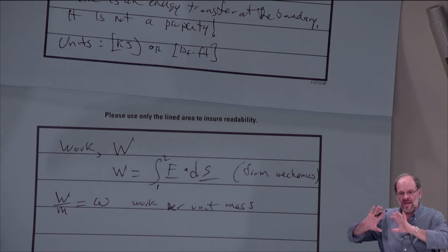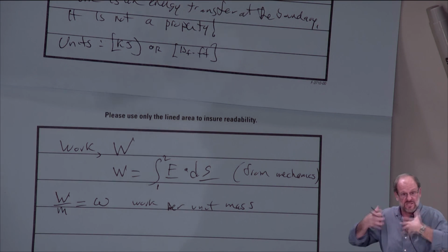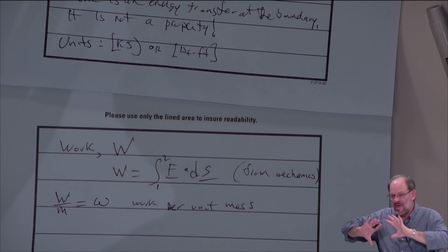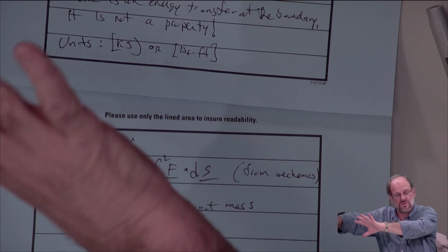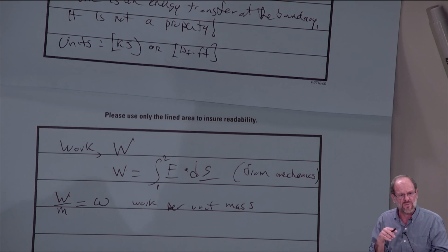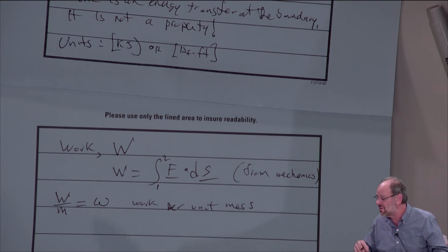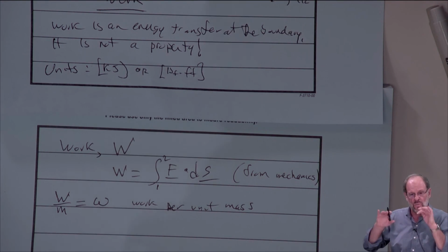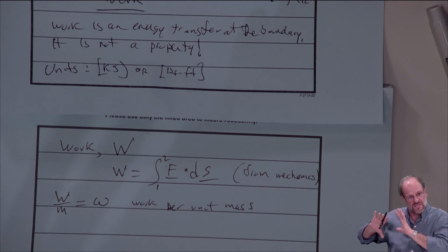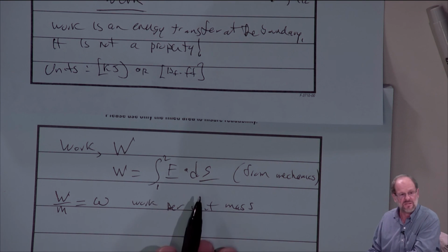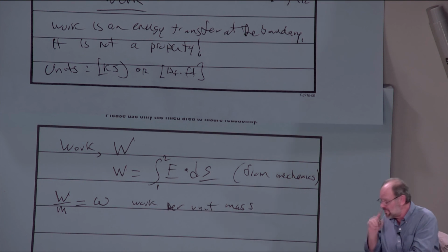So if we are actually, let's say we are the system, or I'm the system, and I'm pushing into the surroundings, then that means work being done to the surroundings by the system is considered positive work. And that's actually opposite of heat transfer, right? With heat transfer, heat added to the system was considered to be positive. Here, work being done by the system to the surroundings is considered positive. And that's entirely based upon the mechanical definition of work.